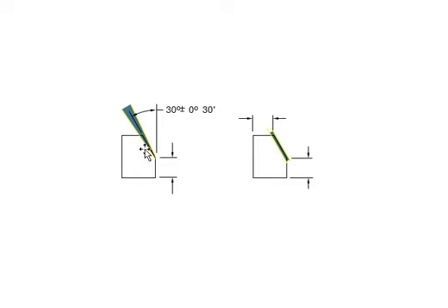Okay, now we're going to see it with a little field color blue right here. So you can see the wedge polar tolerance, and we're going to take the angularity reference out of it. So now you also have this little inclined surface in a parallel zone. Parallel meaning the yellow lines are parallel to each other and your surface is in between them, and we call that a parallel tolerance zone. And this one is a wedge-shaped tolerance zone when we put the reference axis and plane for angularity to dimension the angles.